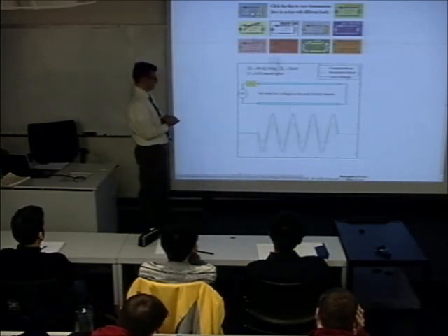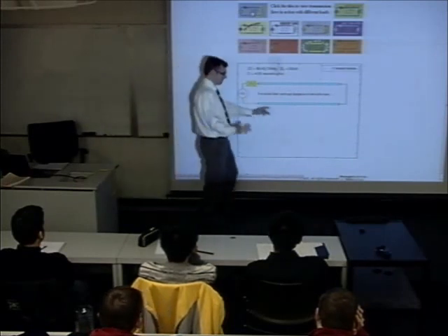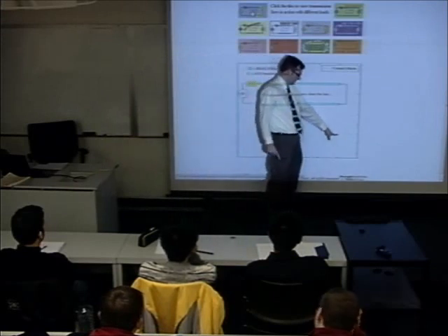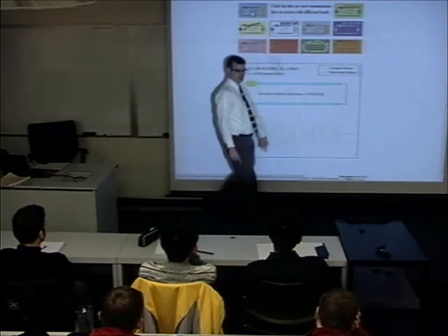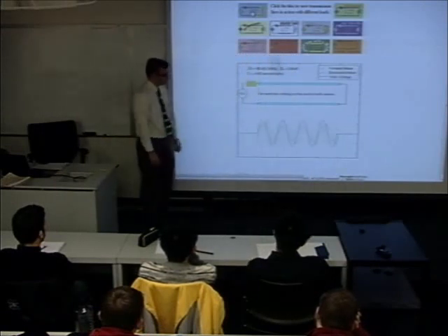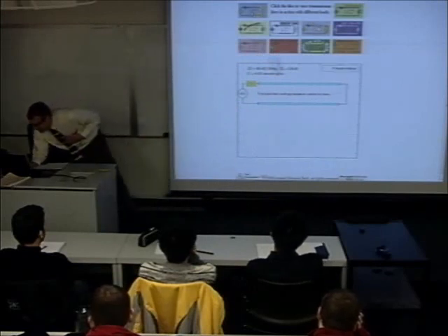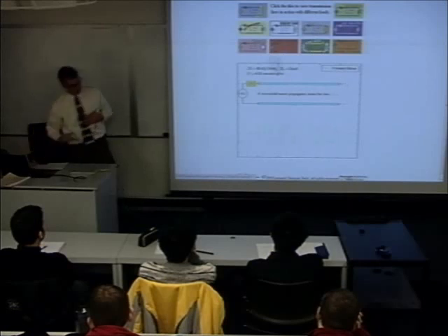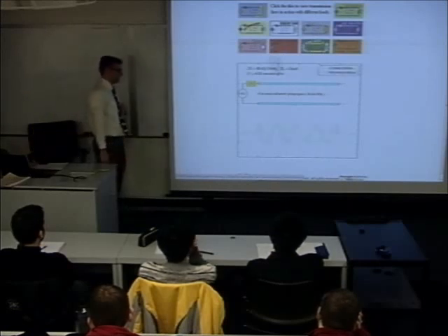So this is the total voltage on the line, the black waveform, and the envelope right there, that blue waveform. You see, consistent with a short circuit, it goes to a minimum of 0 at the end of the line. And it's only when you start moving away from that that it starts to look like an inductor, then an open, then a capacitor, and so on. Not surprisingly, the open circuit looks very similar, except the peak is at the end.